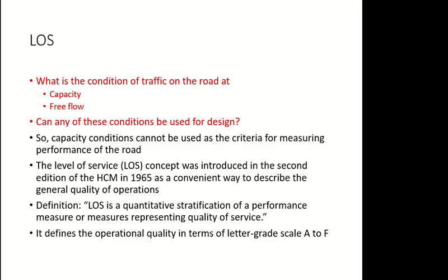So we need to understand different levels of traffic, different conditions of traffic. Having a number for the extreme condition, which is capacity, is not enough, and just focusing on free flow is not enough. That's why they came up with the concept of level of service. So what is level of service? It is dividing traffic flow conditions into different levels, including the extreme levels as well as those in between them.